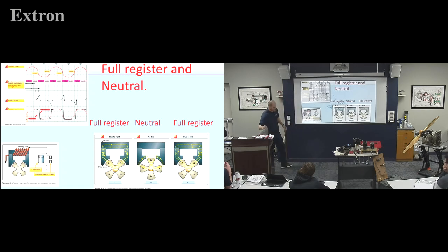But in the neutral position, that's where our flux is changing in the core the fastest. You could say the field is reversing in the primary coil, which then collapses and induces into the transformer. Another way to phrase it is, if I had only a wire, when is the amp draw going to be highest in that wire? At starting, or at building and collapsing? It's going to be when this flux field is changing the fastest.